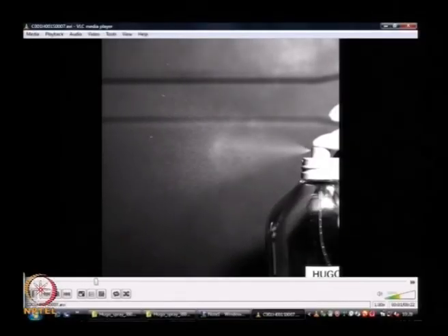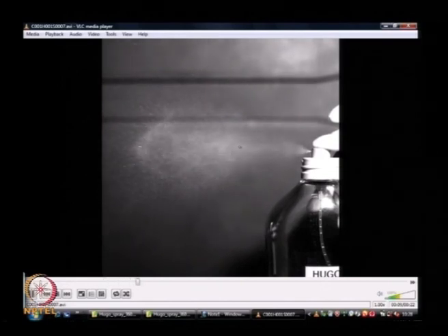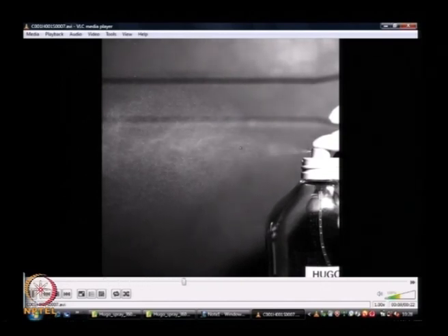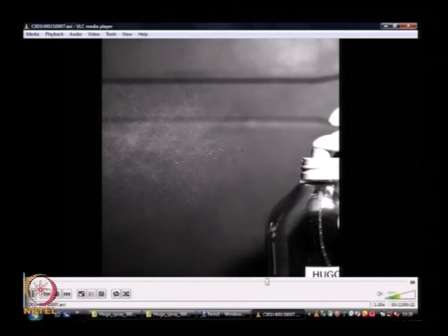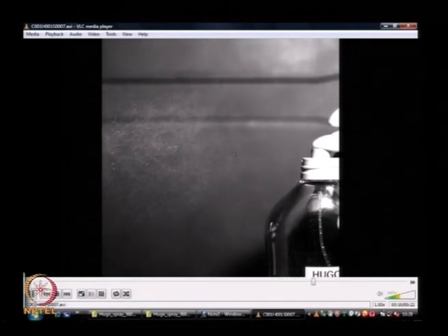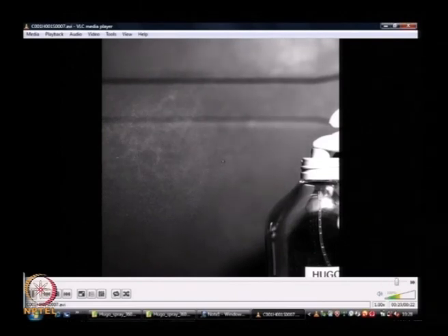is to sit at a point in the spray. So, look at where my cursor is. I will sit at that point in the spray and I have a way of just sitting in a lawn chair and counting every drop that is going by me. Okay, so I am not moving in spatial coordinate, I am just sitting at that one point and acquiring information of the droplet size, droplet velocity, droplet temperature if I want to really get specific about the spray, of every single drop going by me.